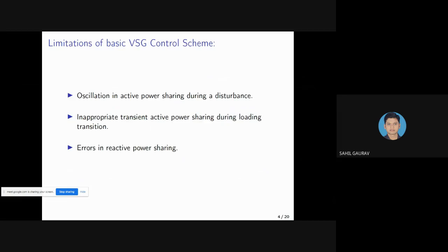This is not a major problem in the case of a grid synchronous generator or alternator, because they usually have considerable overload capabilities. But interfaces in distributed generators are not robust enough to ride through large oscillations. Synchronous generators can manage large power oscillations, but inverter interface distributed generators can't. So this is the critical problem in the case of the virtual synchronous generator, or inverter interface distributed generator.